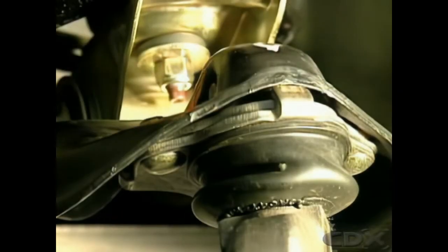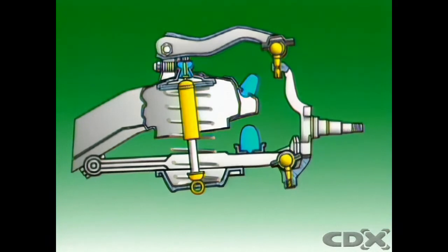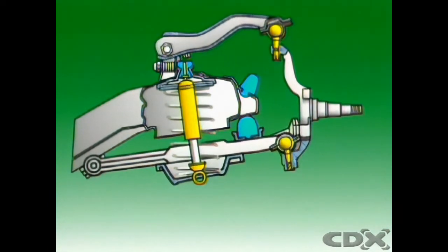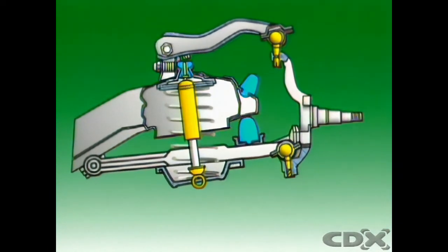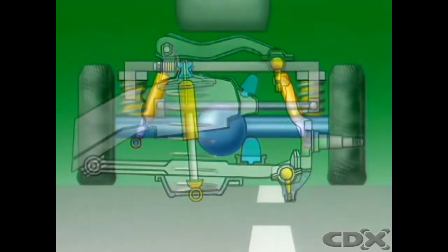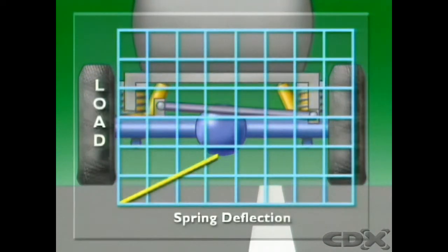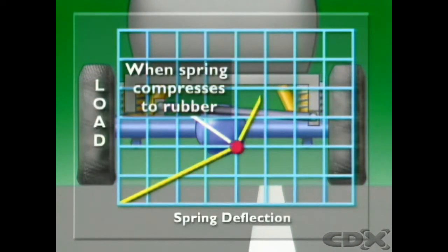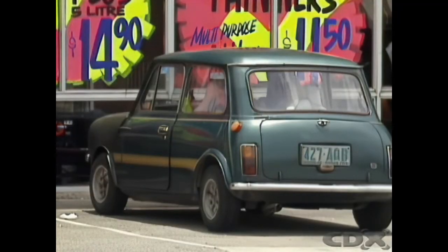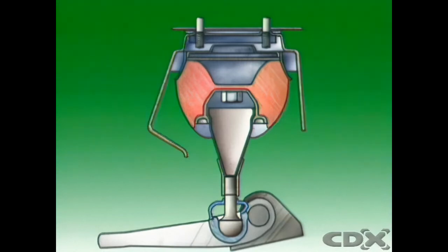Rubber is used in most suspension systems as bump and rebound stops. If the suspension reaches its limit of travel, these stops prevent direct metal-to-metal contact, which reduces jarring of the body of the vehicle. The stops can also be shaped to provide an auxiliary springing function, increasing their resistance progressively with suspension contact. Some vehicles use rubber as the main springing medium.